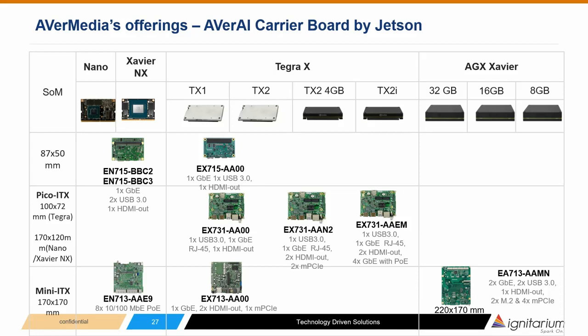Dimension of the carrier boards tends to stay small under the entry and the mid-level spec, like Nano and Xavier NX, for the sake of cost saving, while they are being assigned to perform mission-centric operations that are simplistic and single-tasking. But size increases as the spec leverages to Xavier. Mini ITX boards are equipped with various mini PCIe, M.2 PCIe slots for expandability, where multitasking operations are made available with the same platform.